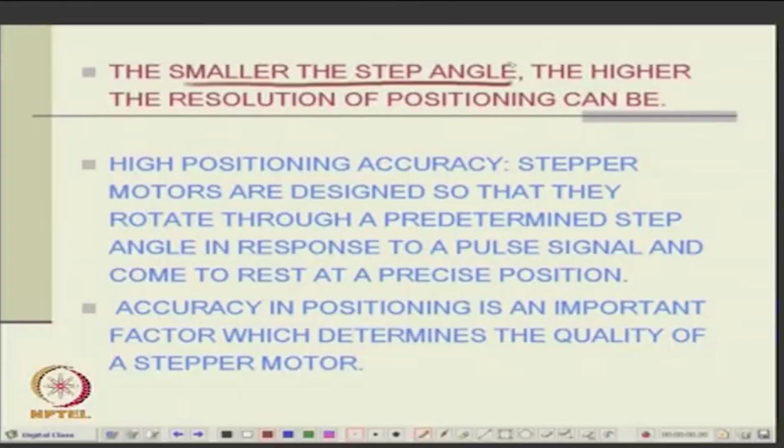And it is very clear, the smaller the step angle, the higher the resolution of positioning. Your resolution is better. I think you know about resolutions. If something can only measure 1 meter, the resolution is bad. If it can measure 1 centimeter, it is better.